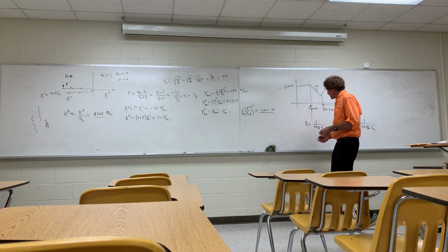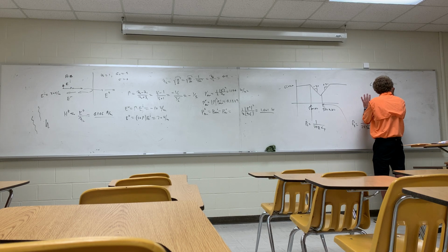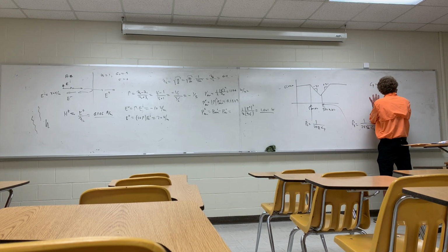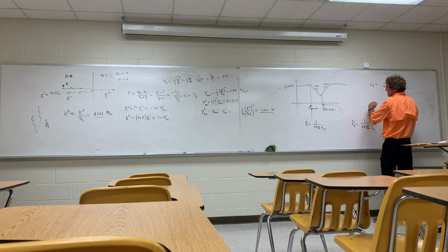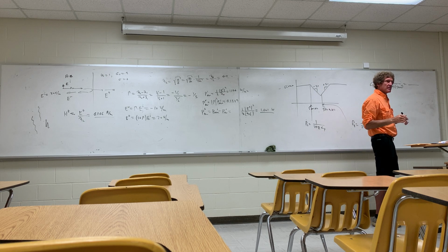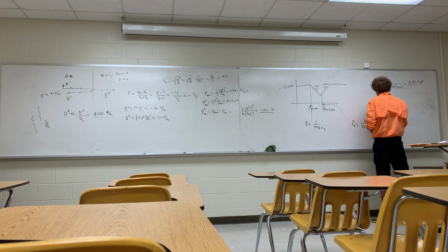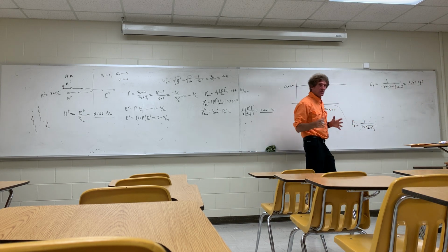So this is simple manipulation. If I want C parasitic, it's equal to 1 over 2 pi times R, which is 6,600, times that frequency, which is 5 megahertz, 5 times 10 to the 6. And can you give that to me? It's going to be about 4.823 picofarads. Picofarad, right? Do y'all follow this?